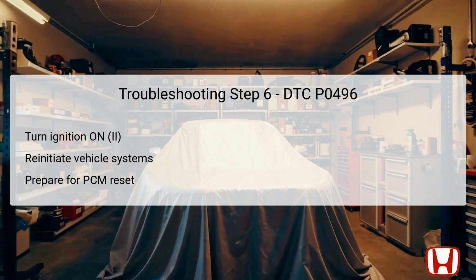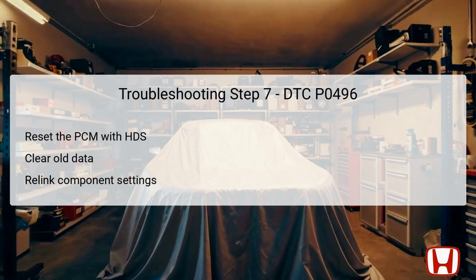Again, using the Honda Diagnostic System, HDS, will aid in this process as it offers clear guidance on how to proceed. The reset of the PCM is essential for allowing the system to recognize the new components and adjustments made during the troubleshooting. The seventh step involves resetting the powertrain control module, PCM, using the Honda Diagnostic System, HDS.